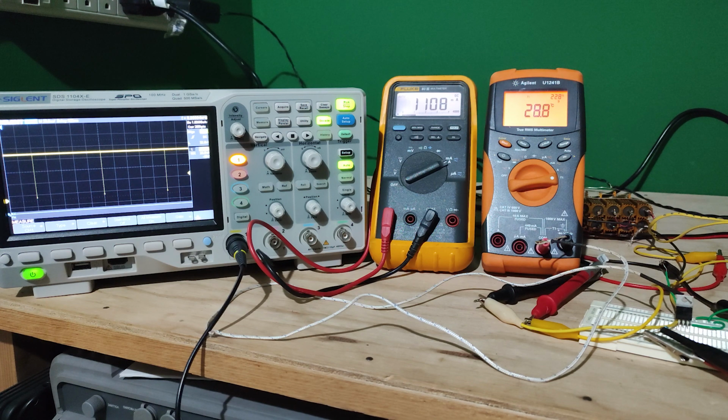So we can see that the PWM signal is providing a more efficient way of controlling the transistor, because we are reaching the amplitude of activation within the transistor, and we are not varying its resistance. We're only turning it off and on, and that's it. We can see that the temperature is staying within the 30-degree range. We have a 50% duty cycle.